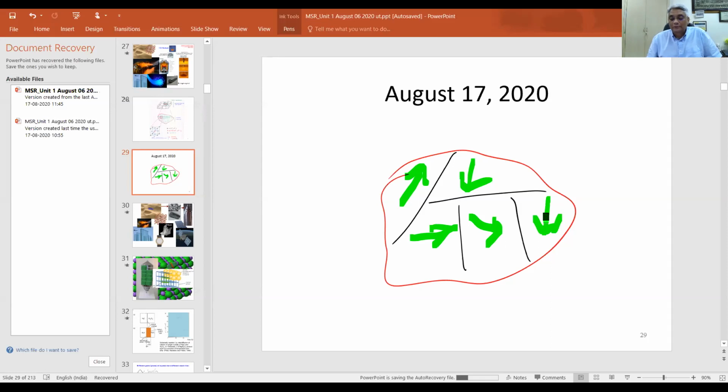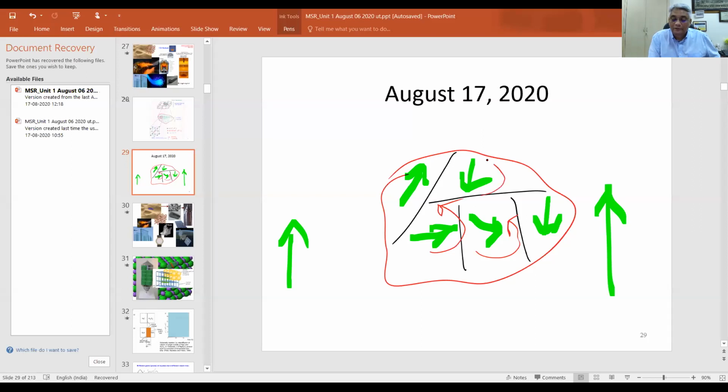This is possible. But if all these dipoles are in one direction, you have a large electric dipole or a large magnetic dipole. That can also be achieved using an applied electric field in the case of a ferroelectric, or an applied magnetic field in the case of a magnetic material. But basically, in that case, these electric dipoles have to surmount the barrier energy to align themselves in the direction of the field.